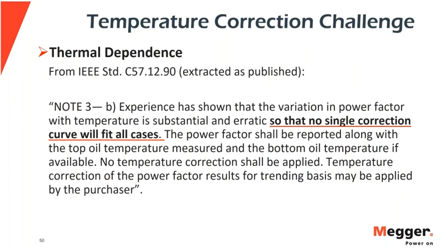When we understood this part, we also understand that the internal condition of your transformer is different from one transformer to the other. So you cannot be generic based just on the nameplate information that you gather as a reference to estimate the correction factor for temperature.